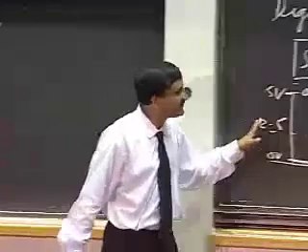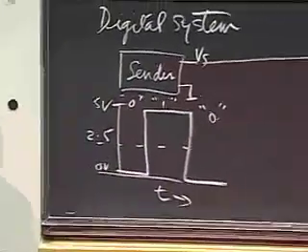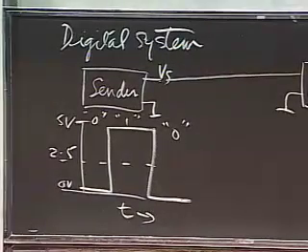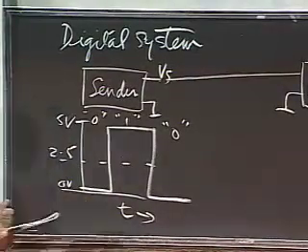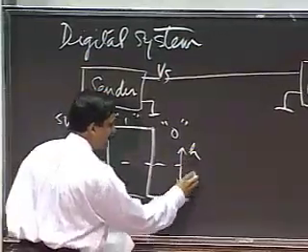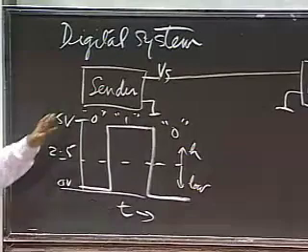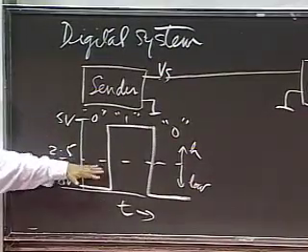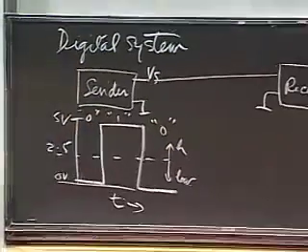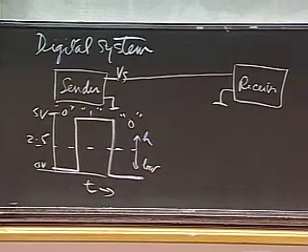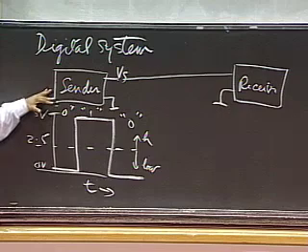This simplistic scheme will not work in many situations, but go along with this for a few seconds. So I send the signal sequence 0, 1, 0 out here, and notice that there is a high and a low. The agreement the sender and the receiver have is that if you see a value that's higher than 2.5 volts, that's a high. If you see a value below 2.5 volts in the wire, that's a low. And I'm going to send zeros at 0 volts or 5 volts from here.